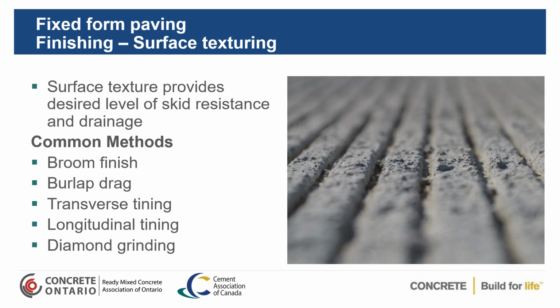Talk about surface texturing. It's important to provide texturing on concrete pavement because that allows you to improve the skid resistance and the ability to drain water from the surface, so it improves your hydroplaning capabilities. The common forms are broom finish, burlap drag, or it could be an astroturf drag,